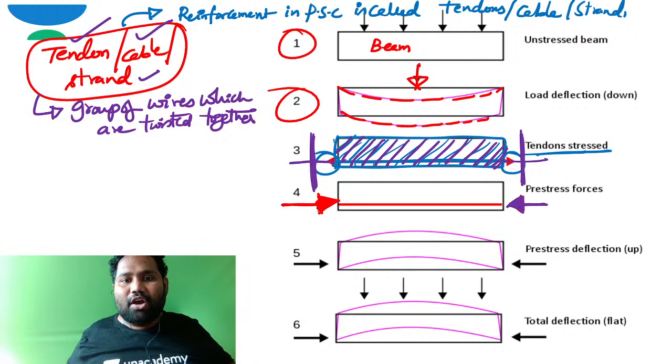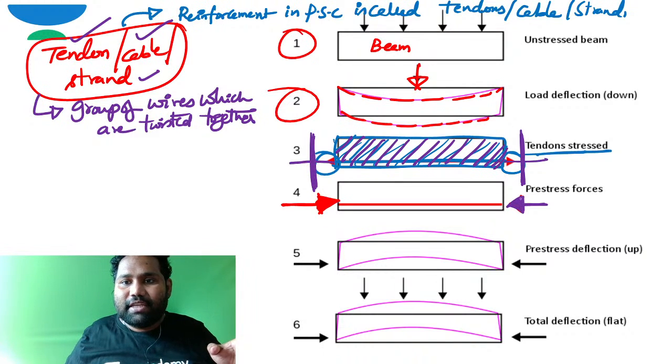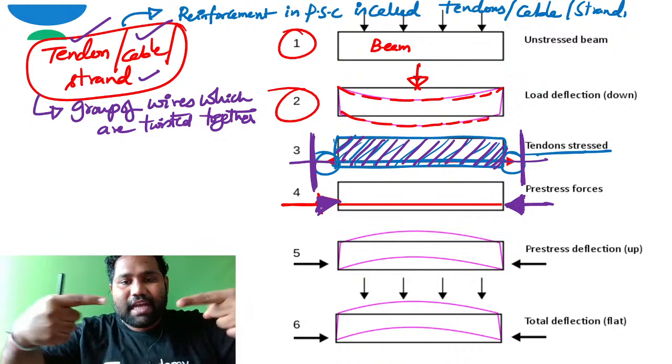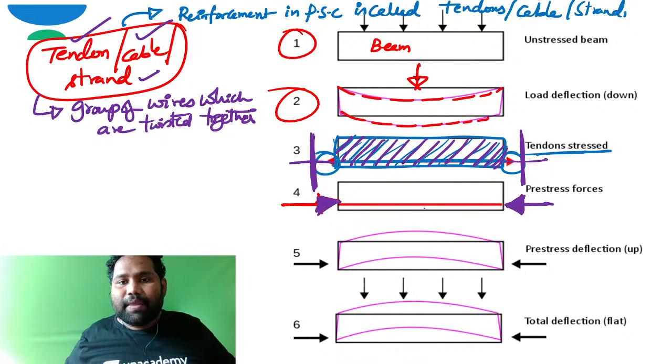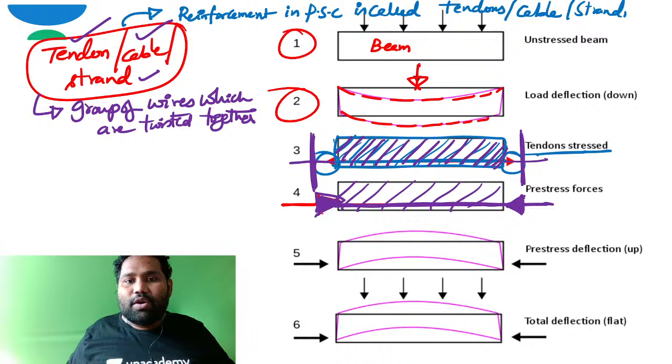So after the concrete has been cast, if I cut these two pre-stresses at the end, the pre-stressing action with the help of jacks, instead of tension action, will be applied as compression action on the surrounding concrete. Take this concrete block, which has a reinforcing tendon. The reinforcing tendon is applying a very good compressive action on the surrounding concrete.